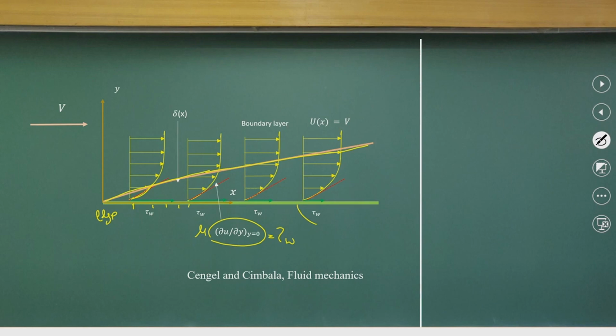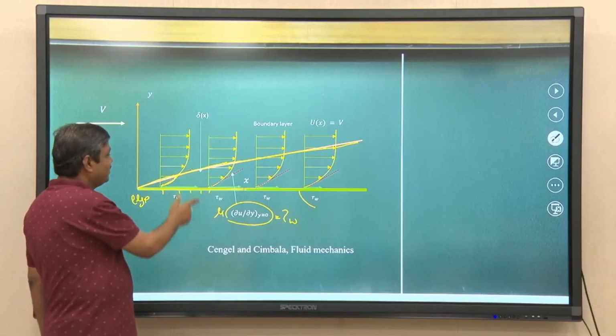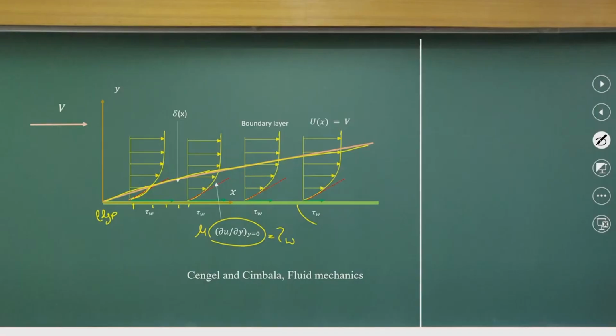So, as the boundary layer formation is happening in the very initial phases, you will have more wall stress, and as you go downstream, your shear stress decreases. So, you will have more shear stress at the front. That is the reason, if you look at aircraft wings, we try to design them in such a way that they can take more loads at the boundary layer parts. Okay. That is the reason, if you look at our forefathers, they used to sharpen the arrows. Okay.